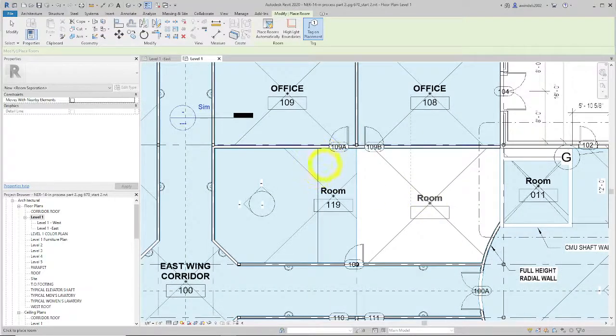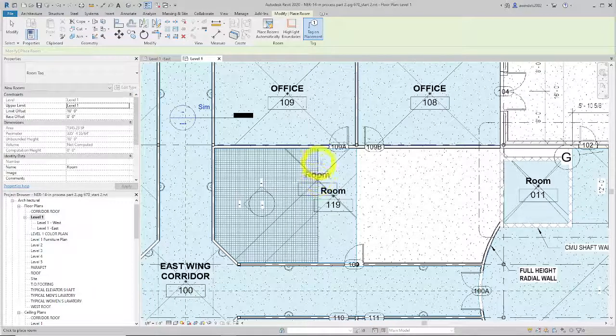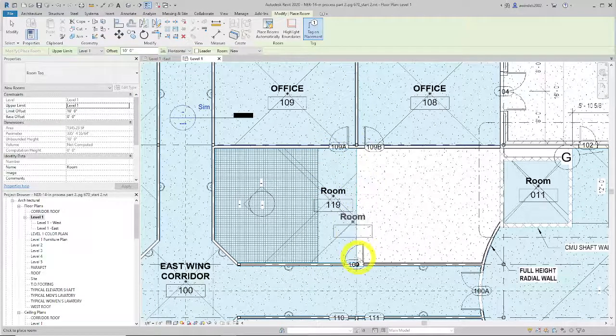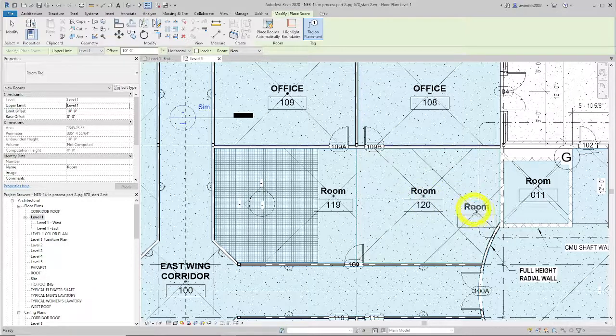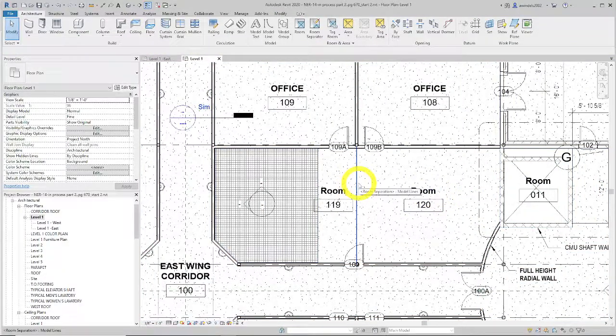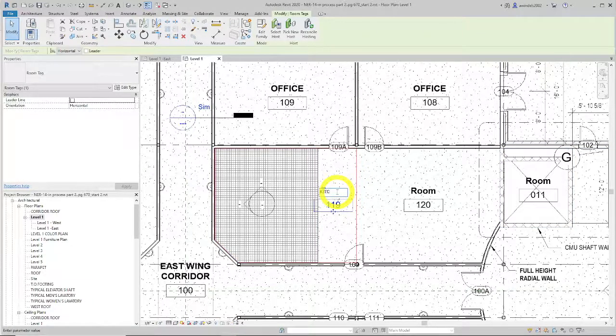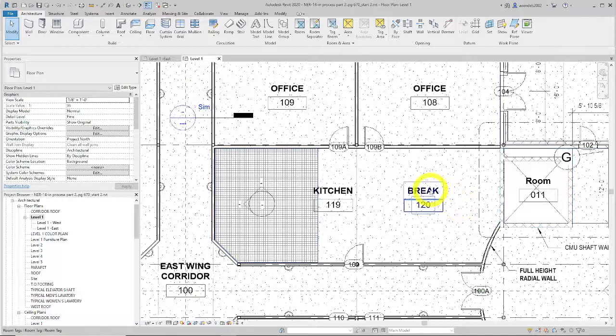Or you could draw it on this line and then later use the pick command, and then you could drag it with its grips over to here. So I just drew a 2-point line here to here. Now it took a minute. It separated it. And now I'm able to build the second room out. It did split them or separate them. So there's a couple ways to do that. Now I got room 119, room 120. I'm just going to rename them to, let's see, kitchen, break room. So that's separating a room. Hover on it, check my work. Okay, here we go.